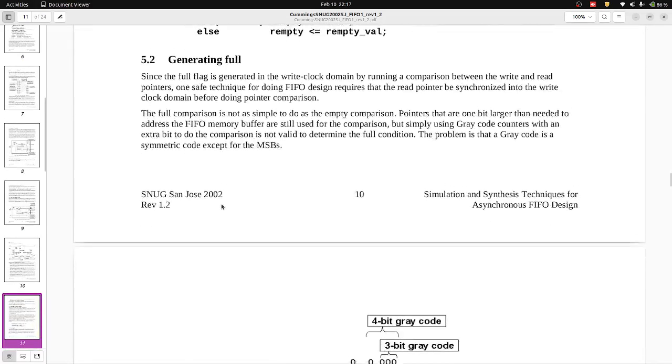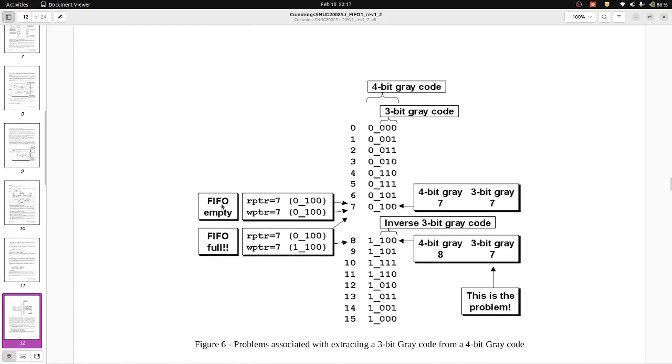We don't want problems in our life, or in our design. In order to avoid that, we use gray code. Gray code is a type of code in which it changes by only 1 bit. You see this is a gray code, and there's only a 1 bit change between each level. Suppose there's a delay while it is going from 1 to 2.